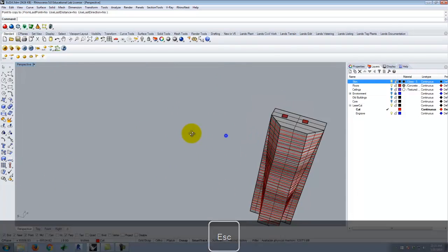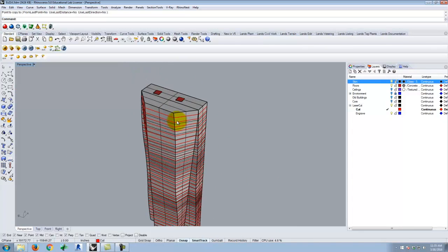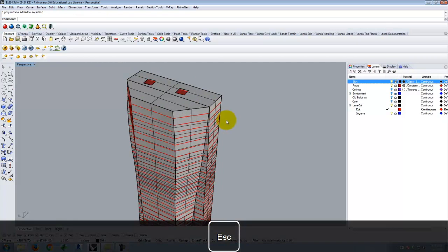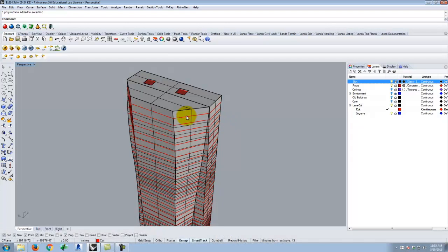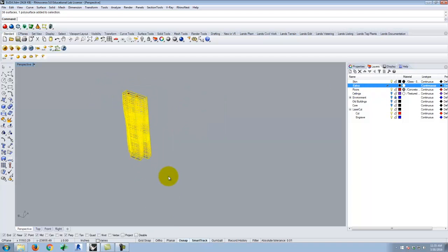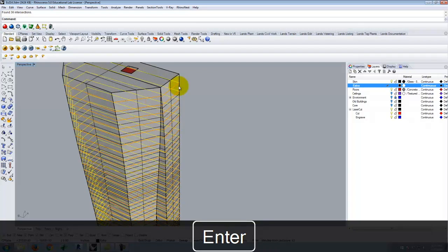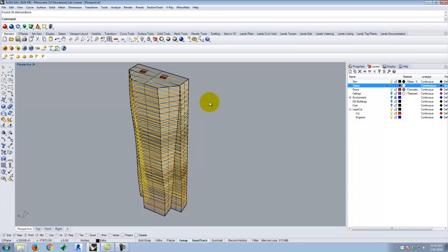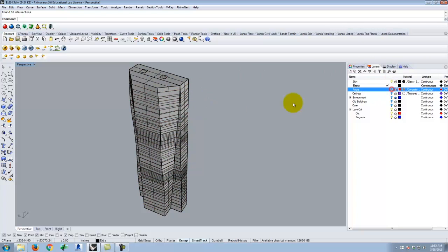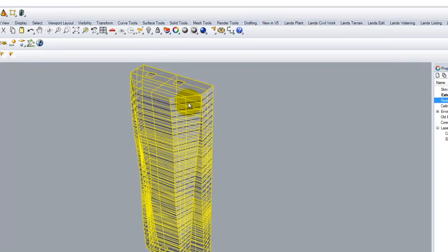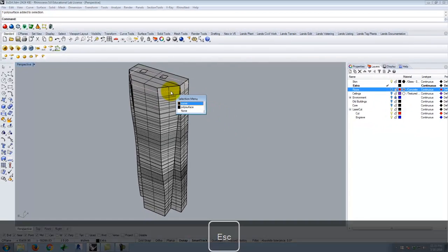Okay, so I have the floors and I have the skin. I'm now going to intersect the skin with the floors to create little profile curves that go around at the edges of every floor. I could duplicate the borders of every floor too. It doesn't matter which way I do it. Let me create an extra layer here. Make that active. And I'll do that intersect. And so now we see that it's created all of those little curves. Okay? At that point, we can turn back off the floors, and we have the skin plus these little curves that go around the object.